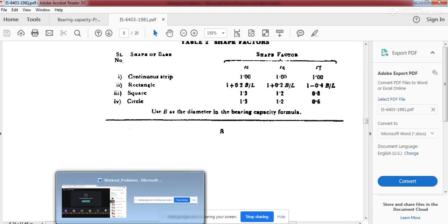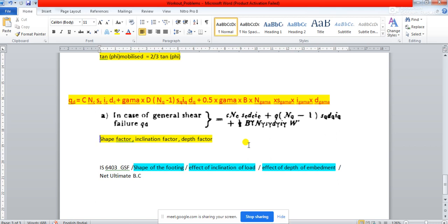Now one confusion may arise. In the previous equation, when we discussed the water table correction factor, if you remember, we multiplied the RW1 or W1 factor to this term and then the W2 factor to this one. Instead, in the Indian Standard Code only one factor is considered. Only the breadth portion of the formula is impacted by the water table correction factor,